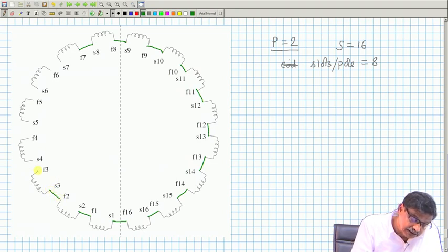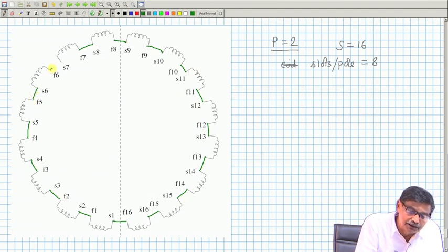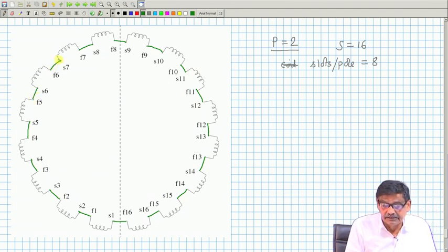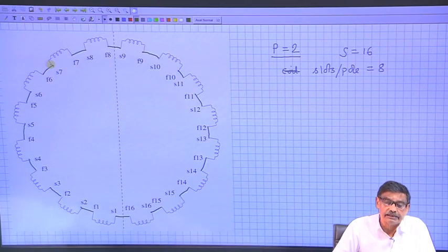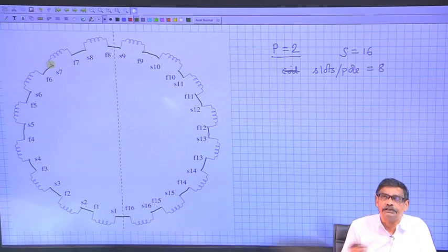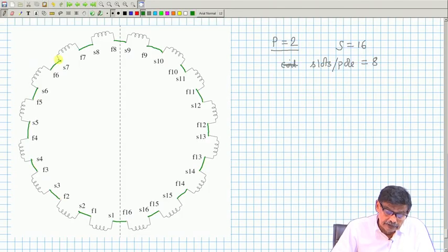So, these coils are connected in series. Will there be any circulating current? No, although each coil will become a seat of EMF, because if I show the polarities of the voltages, as many plus minus voltages as you see in that closed series, so many minus plus you will see, they will cancel each other.